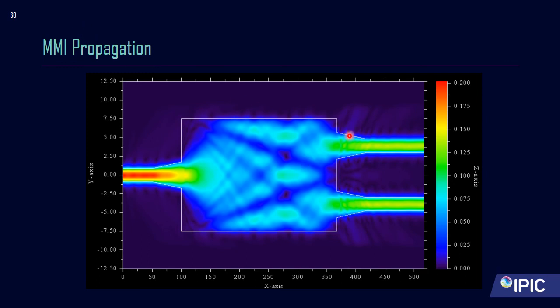For example, if we wanted a 1 input, 3 output MMI with the same width as this, you can see that the three outputs would be located here, here, and here. And if we wanted a 1x4, we'd locate them here, here, here, and here. So the more outputs you want, the smaller the device would get. If you increase the length of the MMI to double this length, then all the light should recombine and you can have one output. It's just the phenomenon of the MMI. It's quite interesting, in my opinion.